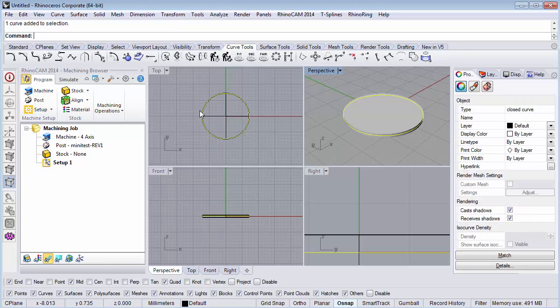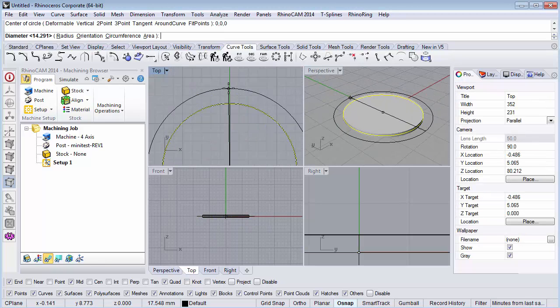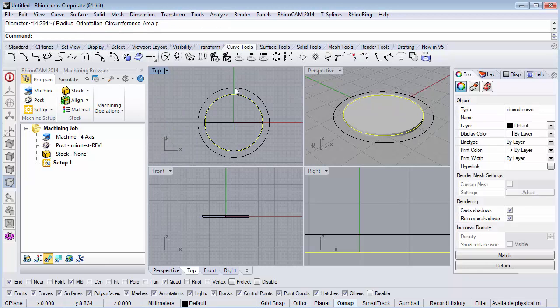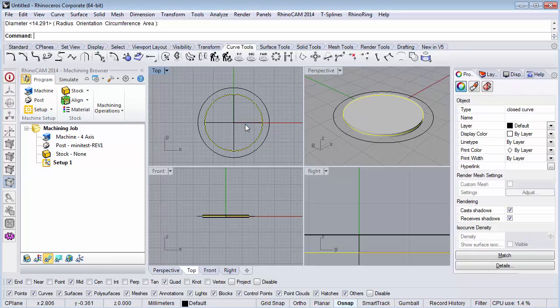So if you know what your piece is, imagine it's a pendant. I'm keeping it simple just for illustration purposes. You need something that goes around the piece that you're going to cut. So I'm going to draw another circle, and you need to put some supports in there, and you need a bit of space to be able to work with it to cut the supports off afterwards. So you put a circle in there like that. How many supports do you need for this? Probably 1, 2, 3 supports or something like that.